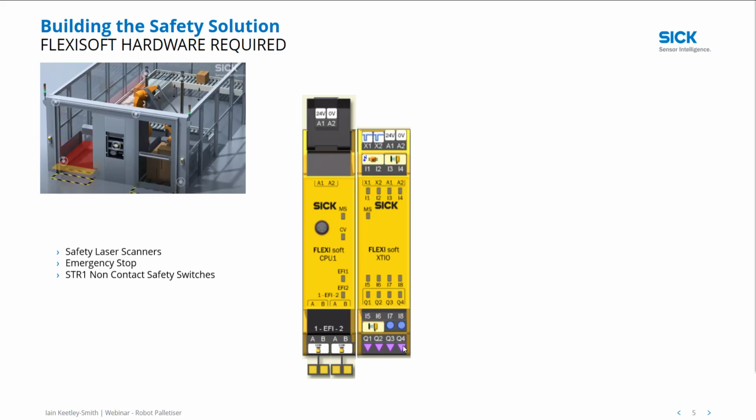In the image of the machine, the switches are located at the top. Up here would be a door switch to indicate the door was closed on this area, and when the robot wants to work in the left hand area, the operator simply slides the door over into this location, and we use these safety switches to determine the position of this door.